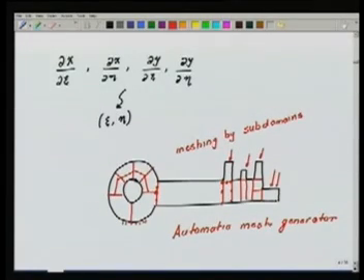So like here on these common edges, these nodes should overlap, and in doing this we can construct a fine mesh where we need the mesh to be fine. We can construct a coarse mesh in the region where we know not much is happening, so we can play around with the meshing and create a non-uniform grid or mesh which is in some way economical and also accurate in terms of getting you the solution.